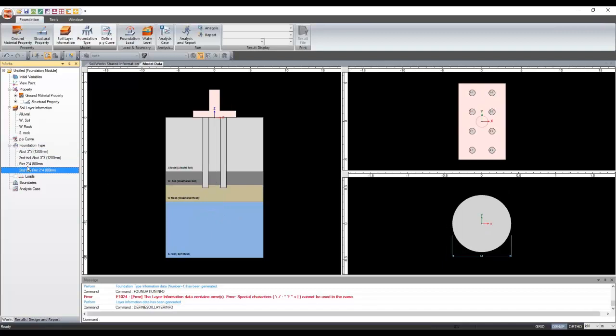Now we are going to determine the P-Y nonlinear curve as well as the foundation stability for the piles underneath the pier. This is your pier with 2x4 piles. This one is 12 meters with 800 mm diameter, and this is a pile of 800 mm diameter, but the depth is restricted to 10 meters only. Now we need to define the loads.